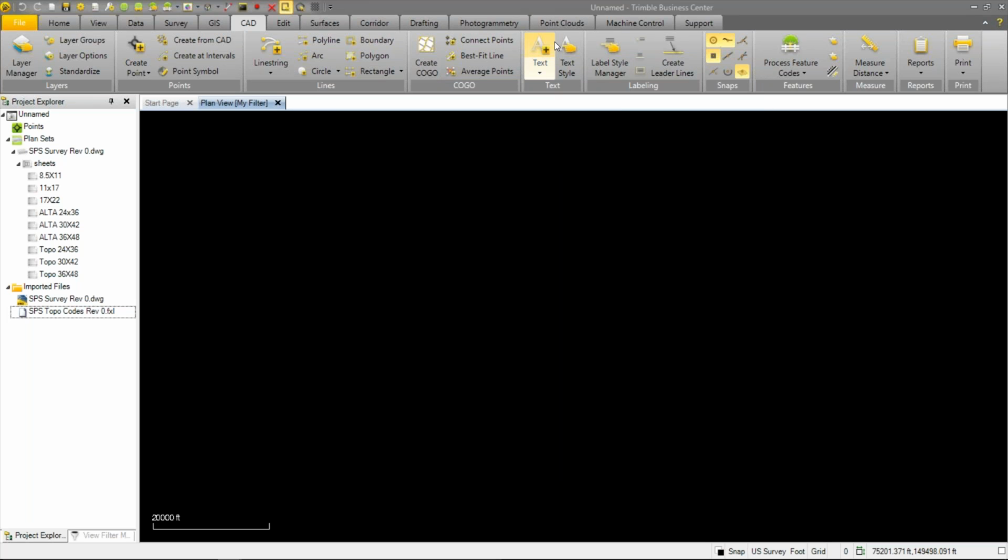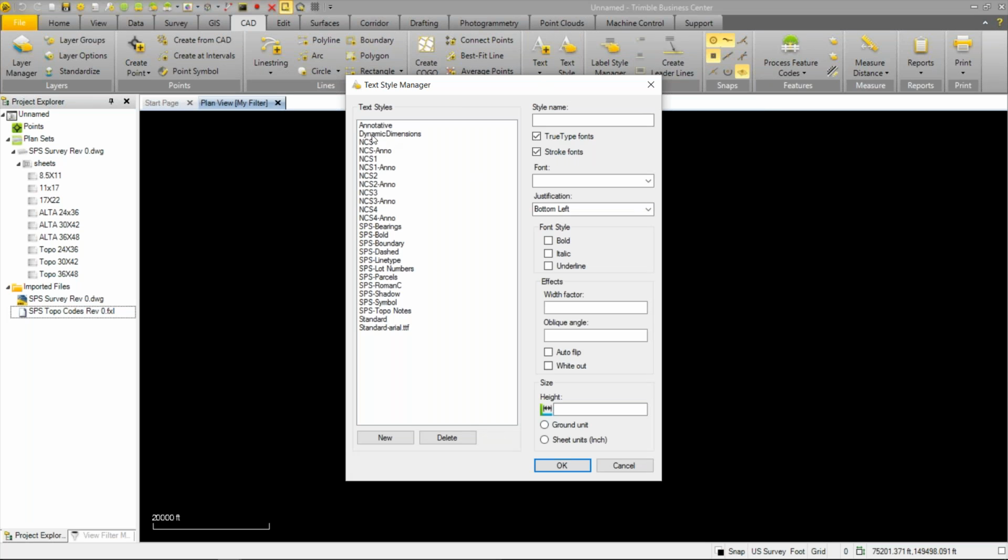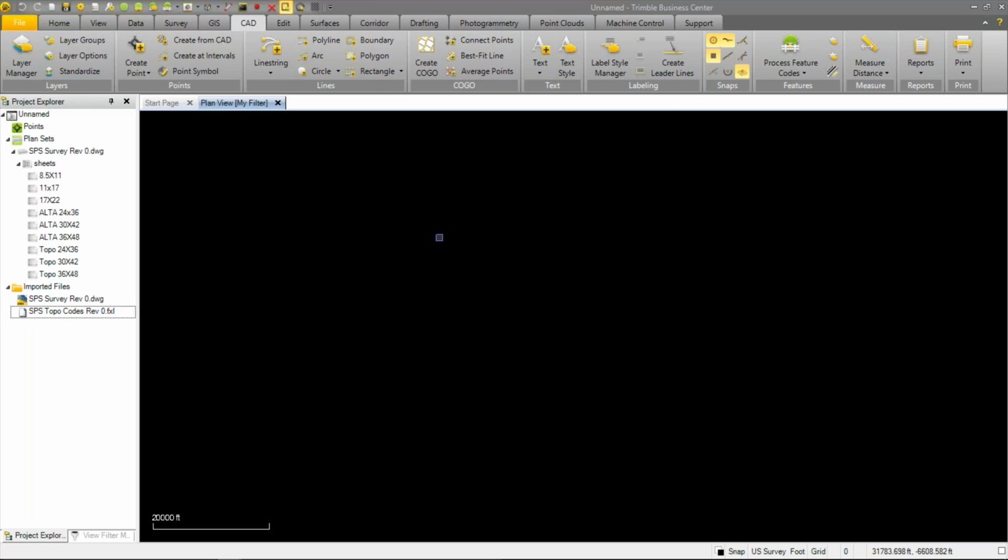So that's set up. You have textiles that came across for all the different textiles that were preset. Line types, I showed you that, textiles, and the layouts. So all those things that were included in your Civil 3D template come across. Things that don't come across are actual point styles and label styles, and that's also a work in progress.